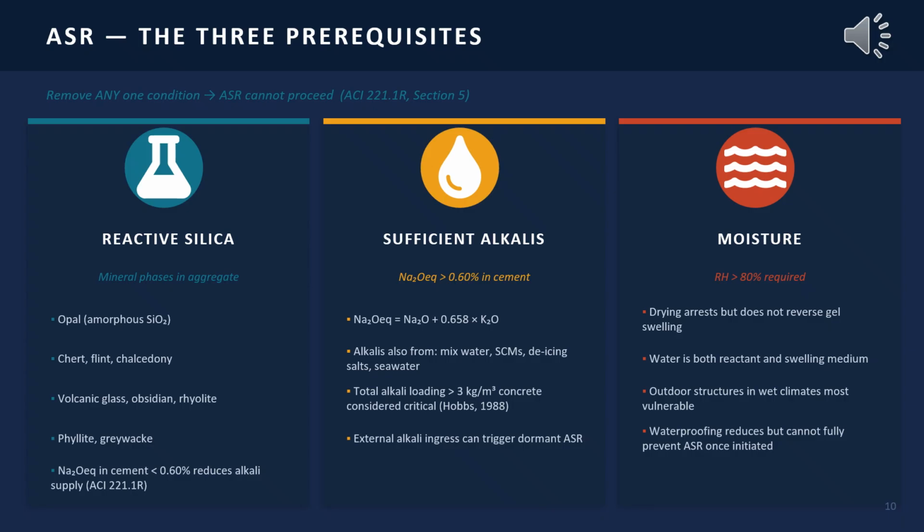Granite, limestone, and well-crystallized quartzite are generally safe. The problematic minerals are those which I mentioned on the previous slide: opal, jet, volcanic glass, obsidian, and the others.